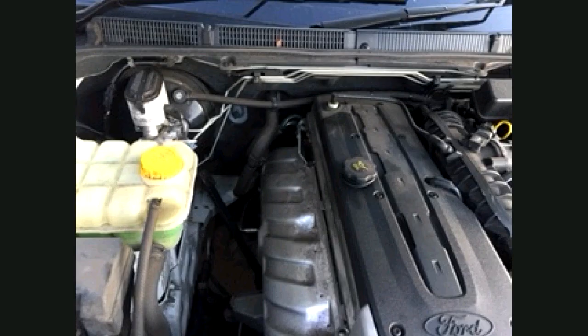Have a look at it underneath the bonnet of your car, or your dad's car, or your mother's car. So this is the engine here, and that is the inlet manifold. And see this here, see that line going across there? That's connected to your inlet manifold. So the air is rushing into your engine there, creating a low pressure. And as soon as you put your foot on the brake, you'll open up this valve and see this big vacuum chamber here. That's the diaphragm. As soon as you open up, this side becomes evacuated of air, and it pulls the shaft through into your master cylinder.